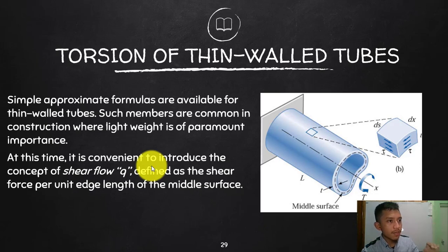So for us to maximize that, we will just focus on the farthest possible. Okay, so we will just consider the outermost. In case we are considering a circular shape, I will consider the circular outer part of the solid. So for me to maximize that, I will only focus on that. Maybe I can neglect the hollow inside, so that will make it a thin-walled tube.